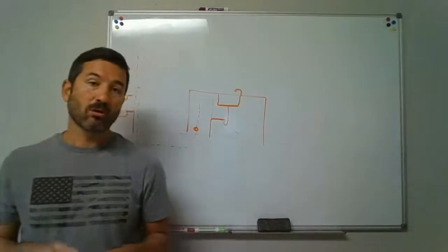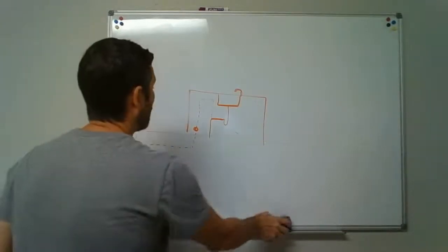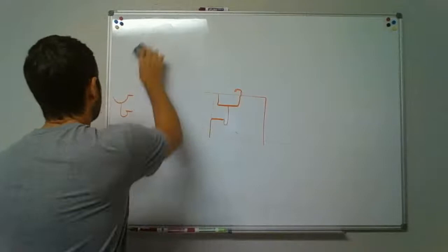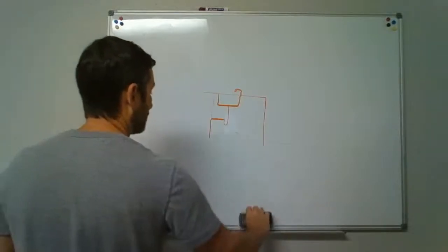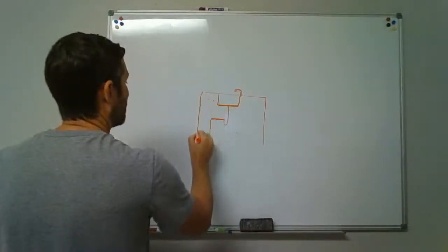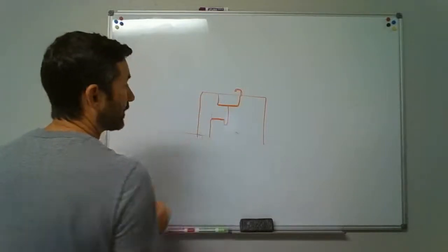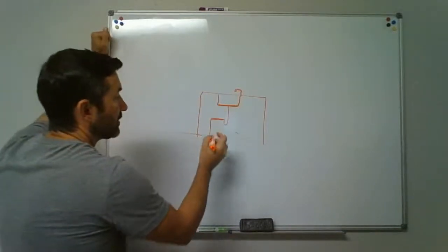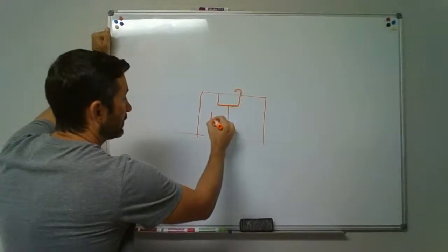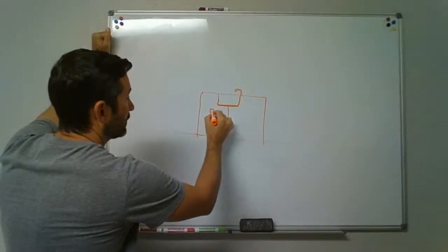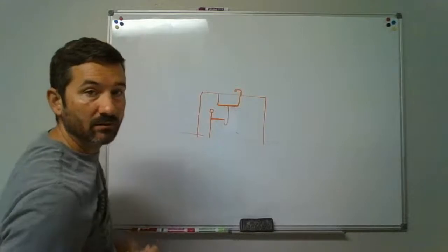So you could go through all that process, or an air admittance valve will allow you just 4 inches, at least 4 inches above the fixture arm. You could put a little auto vent glued up on there.